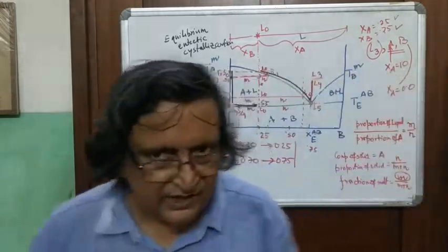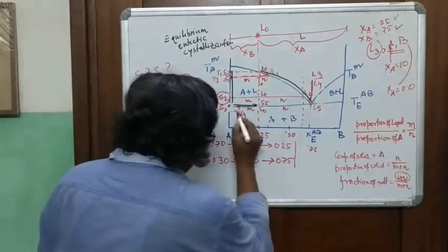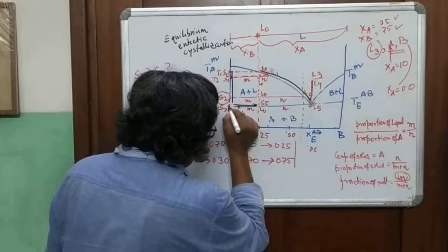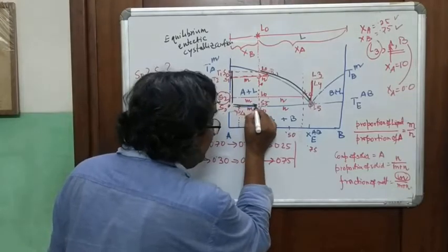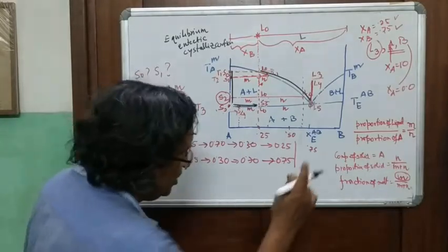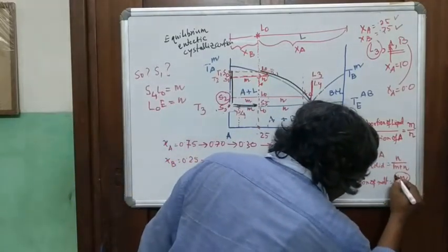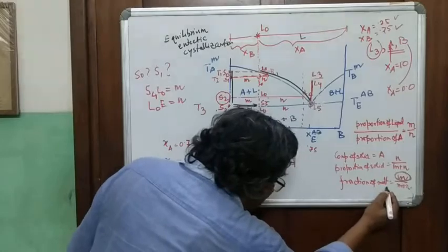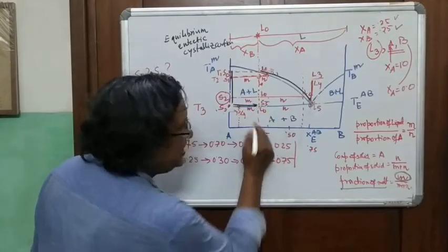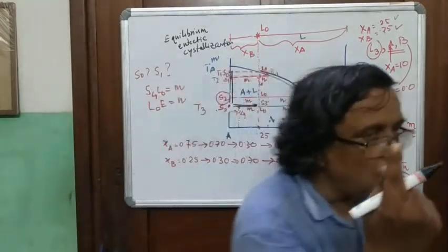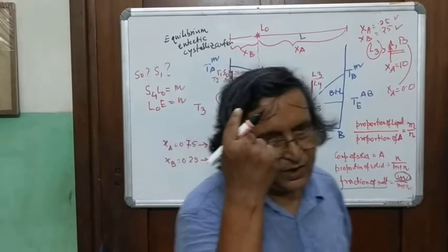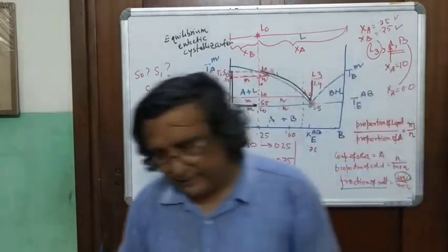And remember this is a very important thing, that as you started to crystallize in the eutectic system, this solid composition started to move inwards. When did the crystallization stop? When M should be equal to 0. That's when the fraction of the melt will become 0. Solid composition and L0 will coincide. That's the only point where M is equal to 0. Have you understood? Okay then.